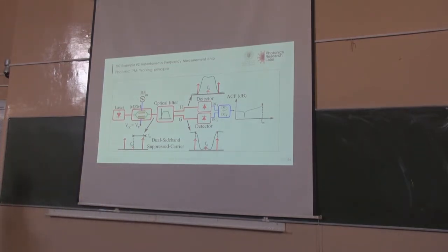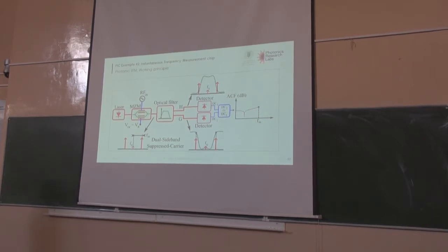Is that clear? Okay, we can see it once more. As I said, low bias, keep only the power on the sidebands. Ideally, you would suppress all this, but in practice you cannot. And then, when the frequency changes, the response these sidebands see from the filter is different. There they see high amplitude, low here, then lower, higher, lower, higher, lower, higher. And then, since you are doing the ratio, you have a range where you can univocally determine the frequency.